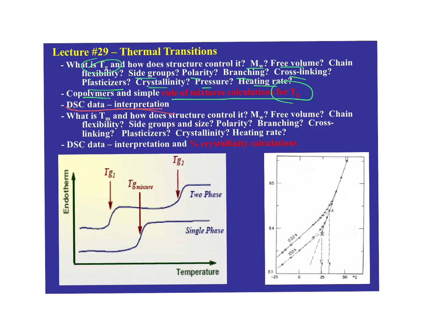And so I can have a copolymer, and if I have AB, AB, AB, I'll get this one in the middle because it acts like a mixture. And if I have 100 units of A followed by 100 units of B, then I'll get separate glass transitions, as they can find themselves and self-associate, and we start to see these distinct features, even though the total amount of A and B in both of these systems could be exactly the same. And so how you arrange them in space controls how they behave in terms of their thermal behavior, and then of course it also controls how they behave in terms of their mechanical behavior.